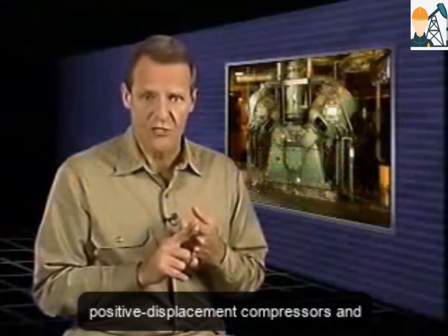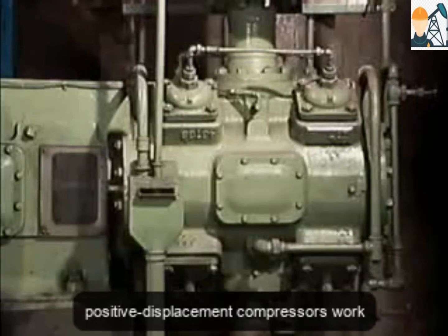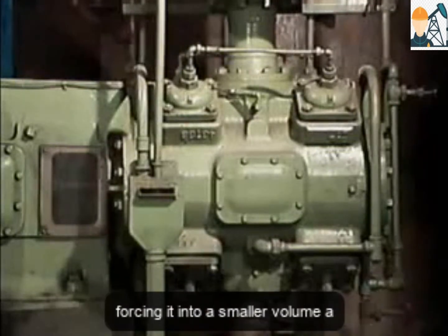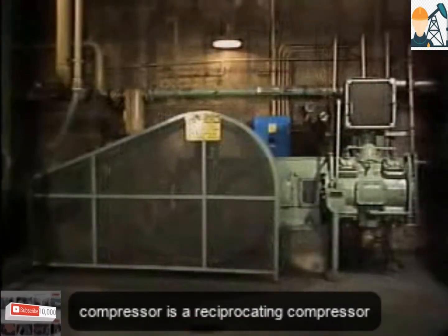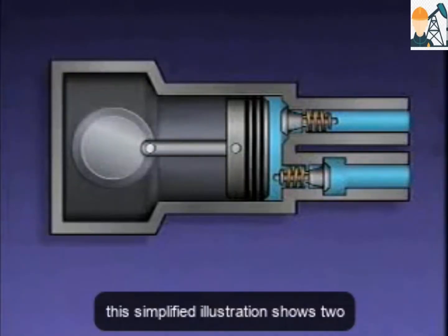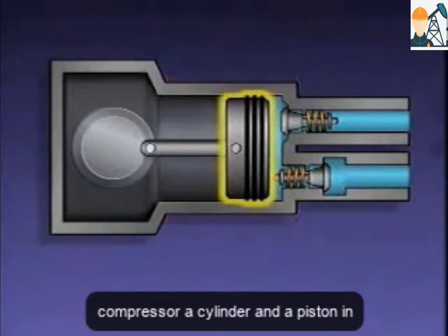Positive displacement compressors, and dynamic or centrifugal compressors. Positive displacement compressors work by trapping a certain amount of gas and forcing it into a smaller volume. A common type of positive displacement compressor is a reciprocating compressor. This simplified illustration shows two main parts of a typical reciprocating compressor: a cylinder and a piston.